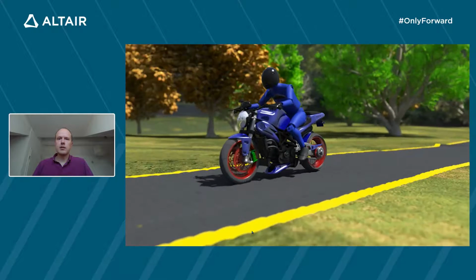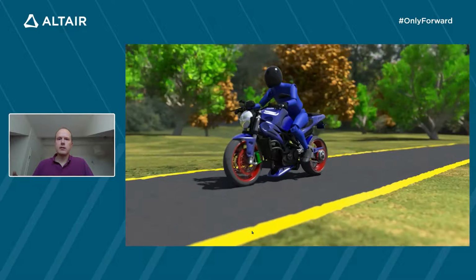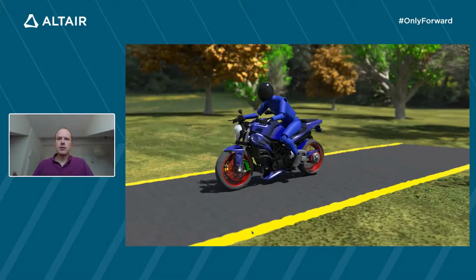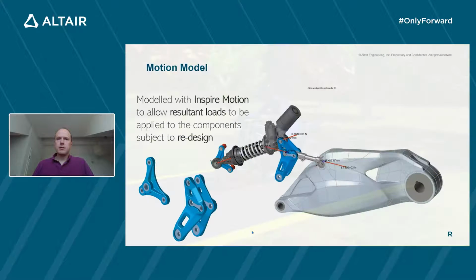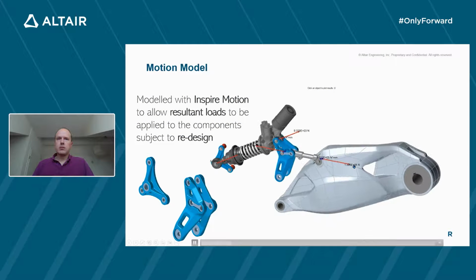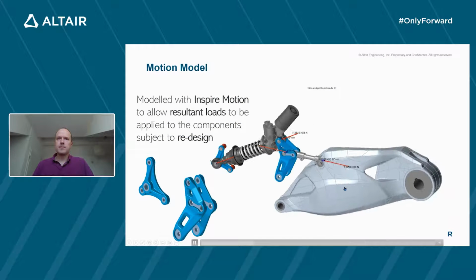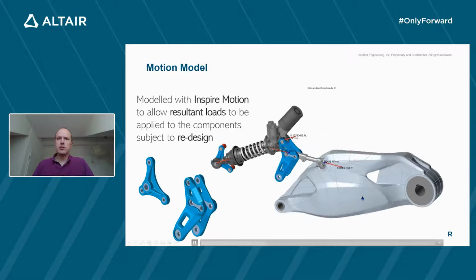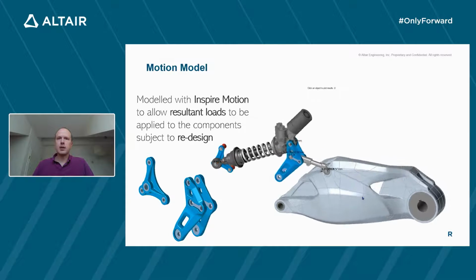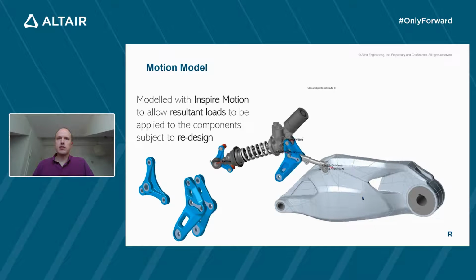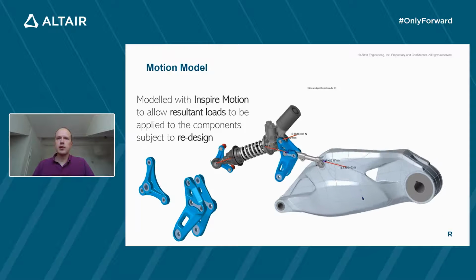You will define the different couplings between the different parts, and from there can deduct the forces acting on the different parts. Okay, now this assembly here is already showing you the animation result, and in the following demo, I will show you within Inspire Motion how to set up this sort of motion multi-body analysis.